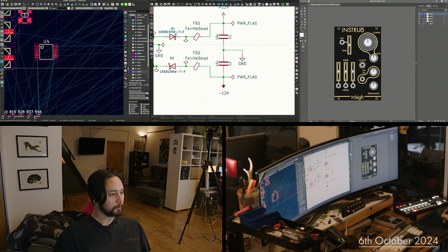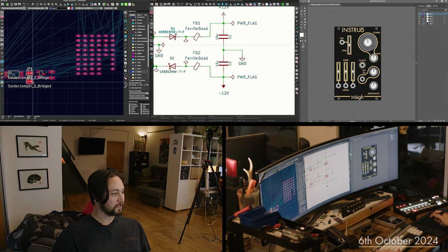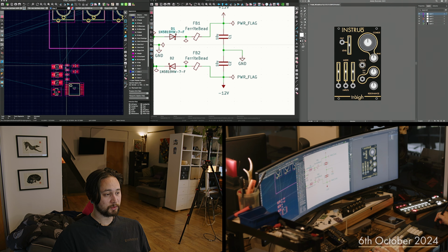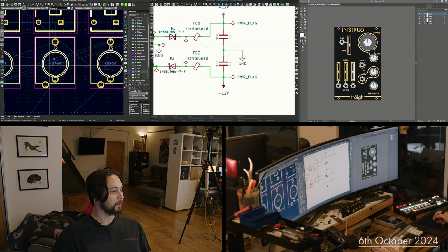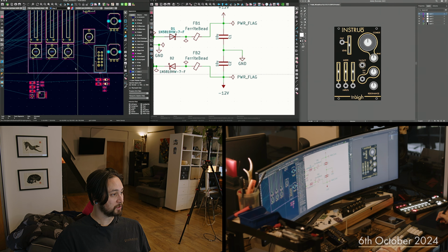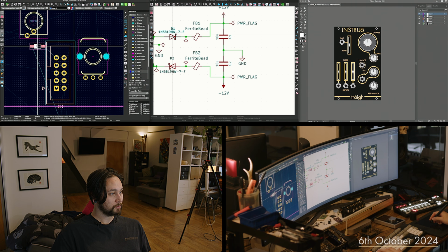Yeah, it's quite neat. And fab layer is, so that's a non-visible layer, so that does export with the Gerbers typically, I think, the way that I export it all. But I can hide all them just now because I don't need to see them. It keeps it a bit cleaner for dragging stuff around.